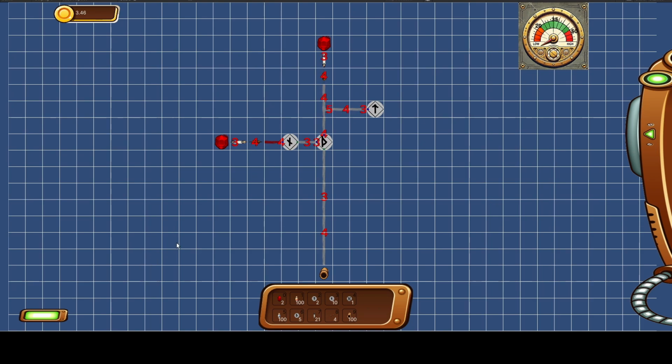So what we will be having, as far as the resistors go, are resistors that have higher power ratings so you can use them in more high power circumstances. Similar for the fuses, where they will have higher power ratings so that they won't fry if you're sending too much power, because you do have to send a good amount of power often. Like you can see this thing's set up for 20 watts. If I was trying to send 20 watts through here, I'm going to fry that, because they can't handle 20 watts. They can handle 5 watts.